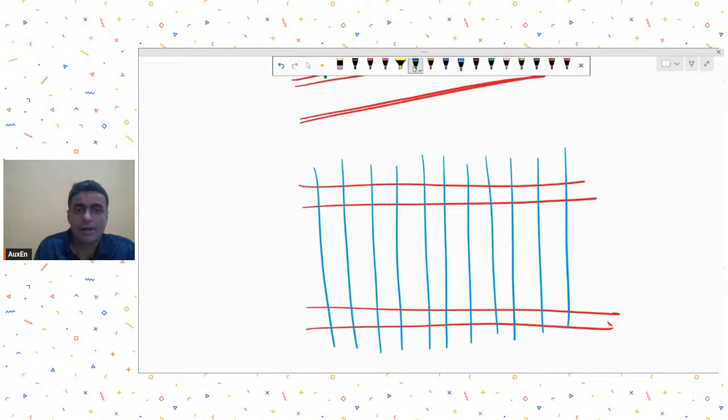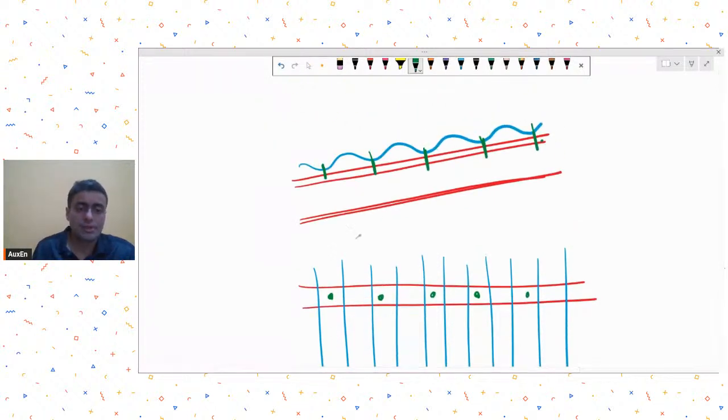Each valley will be connected by a bolt, and this will happen on all purlins also. So this is the way you will find the sheeting is connected to your purlins, and these are usually called self-tapping screws.